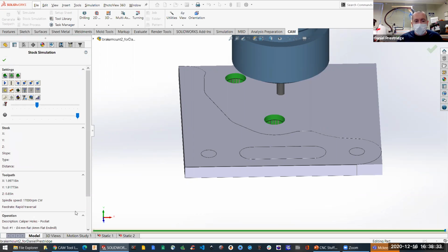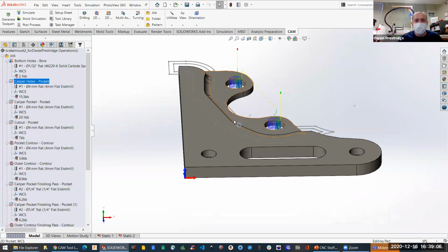After I'm done with all of my stuff, I like to start with a block like this and run through each one of the tool paths and see if the machine is telling itself to do anything crazy. It might drill here and then go over here and do some weirdness and go back over here. I'll say, oh, maybe I accidentally selected this little edge and I wasn't supposed to, and it thinks that it's part of the cut. So it gives you a good idea. So I think that addresses maybe some of the concerns moving forward.